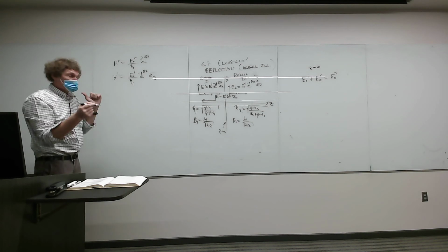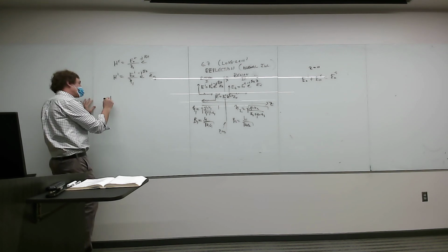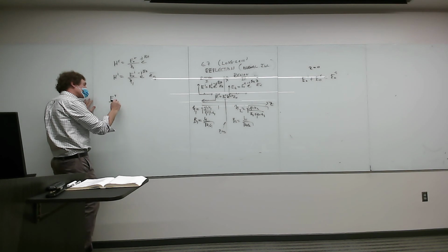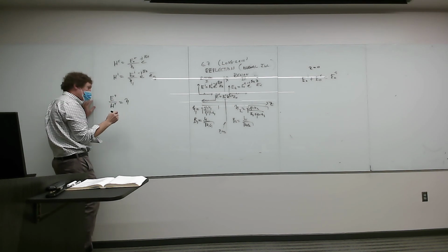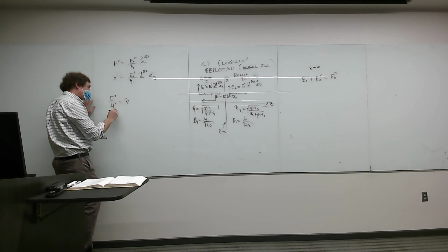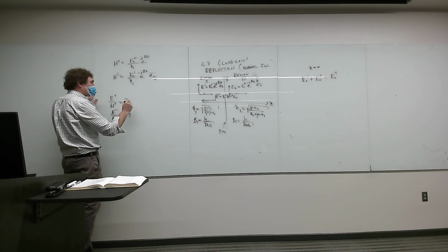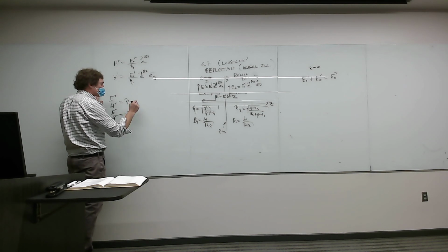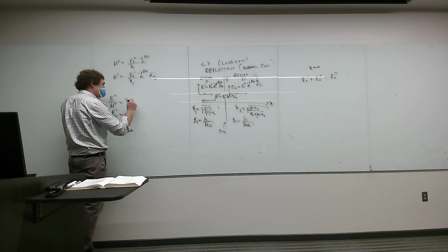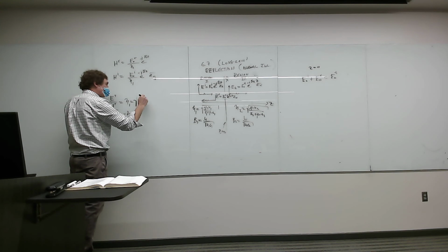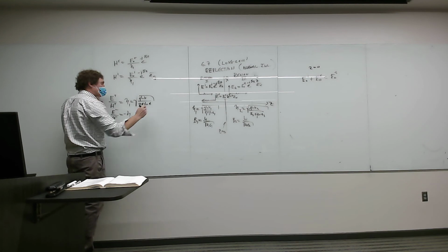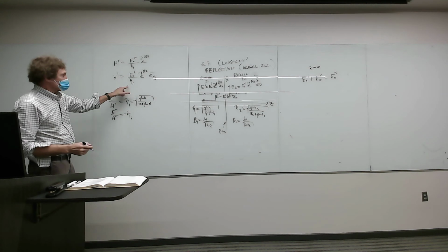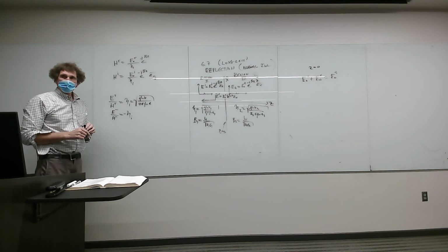When I said that eta, the ratio of E for a positive propagating wave over H positive, was equal to eta, right? But if you have the ratio of a negative going wave, it's minus eta. And again, eta, he calls it intrinsic, but it doesn't matter if you put a sub i here, is equal to the square root of j omega mu over sigma plus j omega epsilon. Here we're assuming sigma 0, but there'd be a phase angle I have to worry about. Agreed, class?